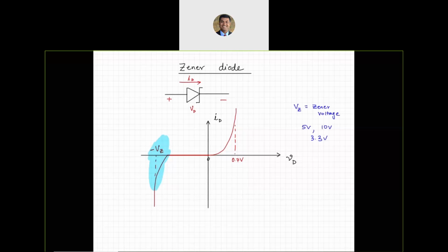Now, if you think about any circuit that you might have, so when we were using the digital circuits, what did we have? For digital 7400 series ICs, we were building some JK flip-flops and counters and simple logic gates. All of them required VCC, supply voltage of 5 volts, positive 5 volts.